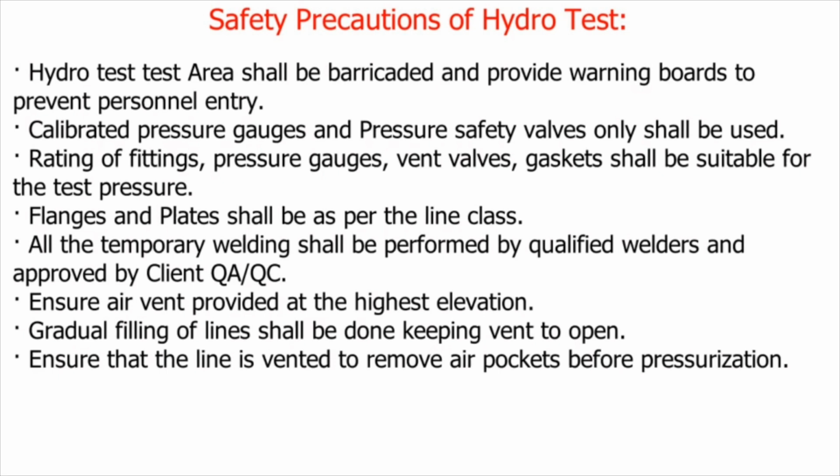All the temporary welding shall be performed by qualified welders and approved by client QA/QC. Ensure vent provided at the highest elevation. Gradual filling of lines shall be done keeping vent open. Ensure that the line is vented to remove air pockets before pressurization.